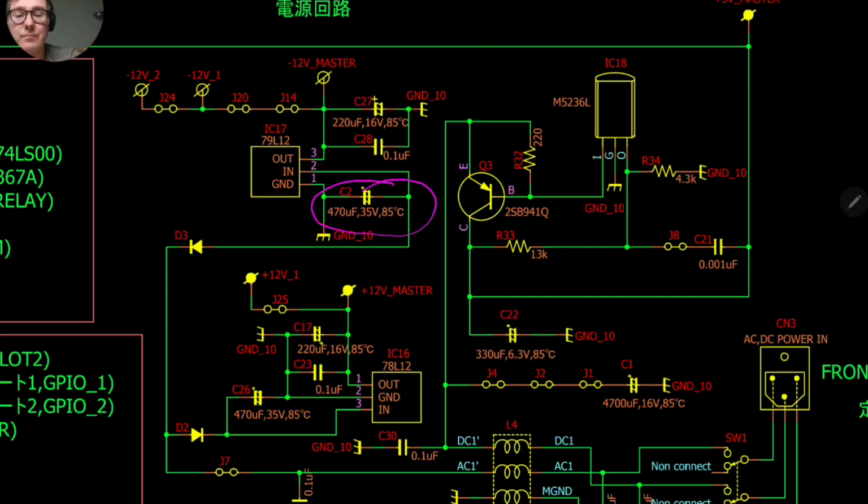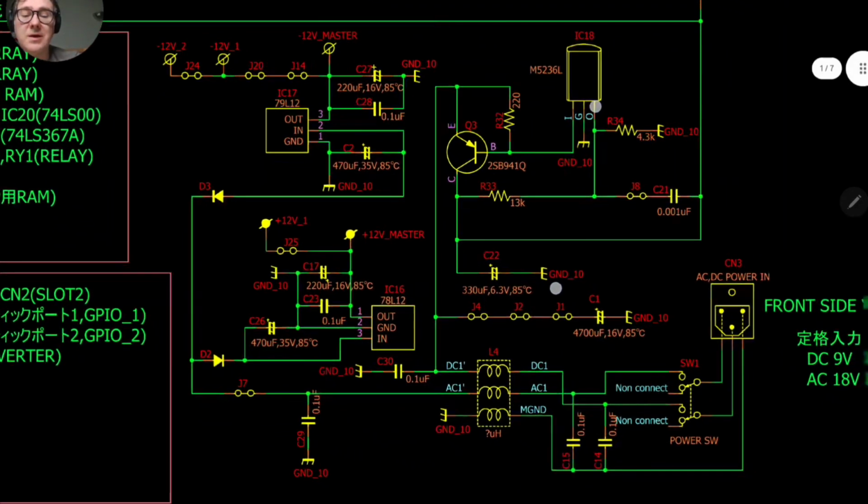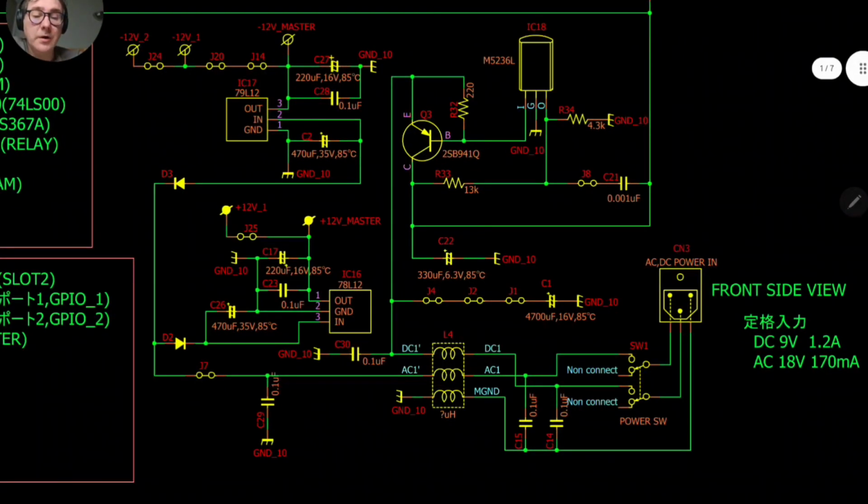the ripple. Here you can see that the plus sign is on the other side, because here we have a negative tension. So you need to reverse the polarity of this capacitor. And it's kind of the same. You have a large capacitor here, a small one to stabilize, and finally you have your minus 12 volts. That's it. So this is the way the power generation works.